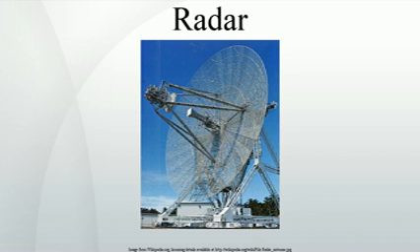The modulation index riding on the received signal is proportional to the time delay between the radar and the reflector. The amount of that frequency shift becomes greater with greater time delay. The measure of the amount of frequency shift is directly proportional to the distance traveled. That distance can be displayed on an instrument, and it may also be available via the transponder. This signal processing is similar to that used in speed detecting Doppler radar. Example systems using this approach are AZUSA, Mistram, and UDOP.